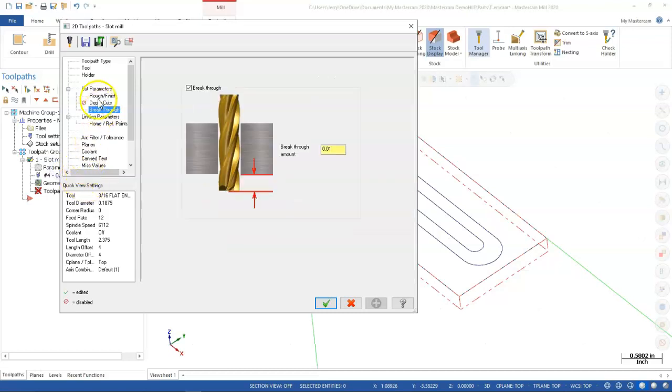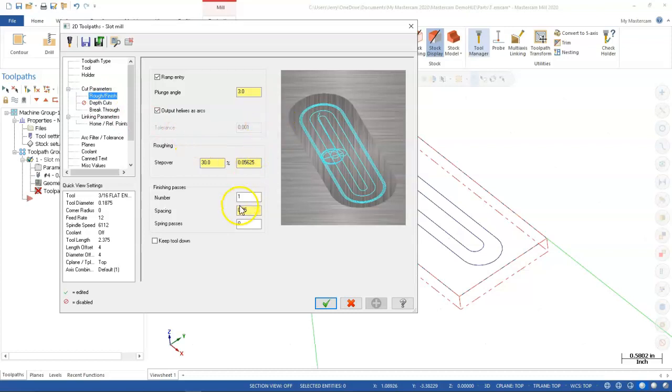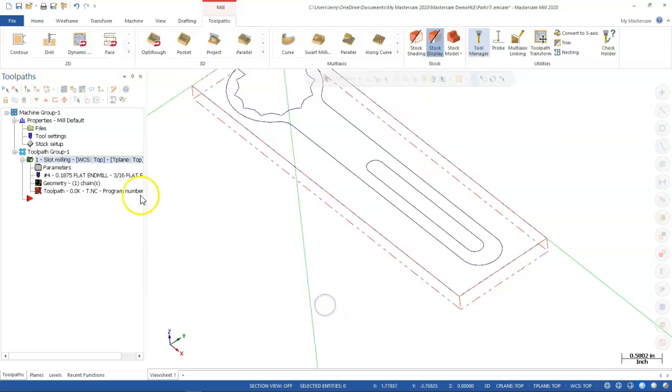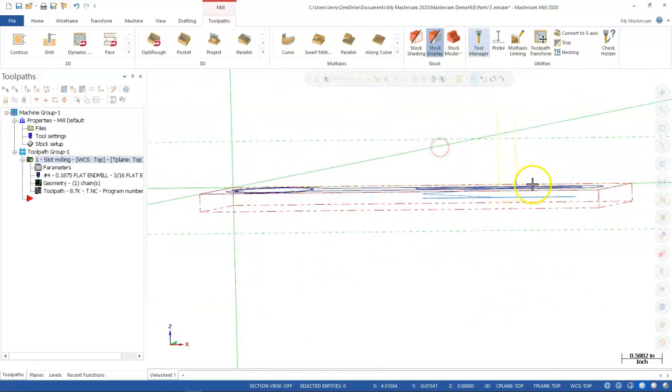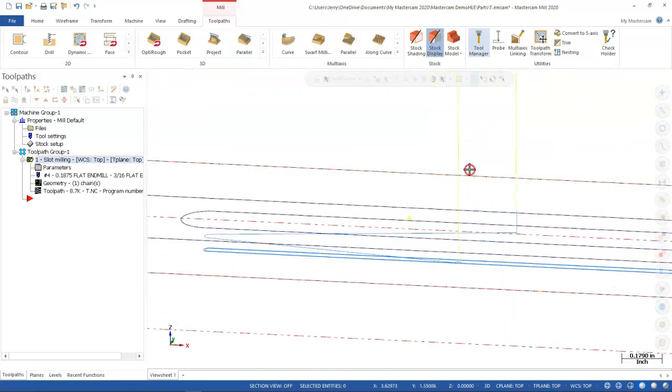So let's run back through, depth cuts, rough finish. I think that spacing, let's go down to 5 thousandths on a finish pass and see if that takes care of it. Anything that steps us off that wall, to where the radius diameter of that tool can't fit into that slot, we've got to identify that and make sure it has enough room to build that entire travel.